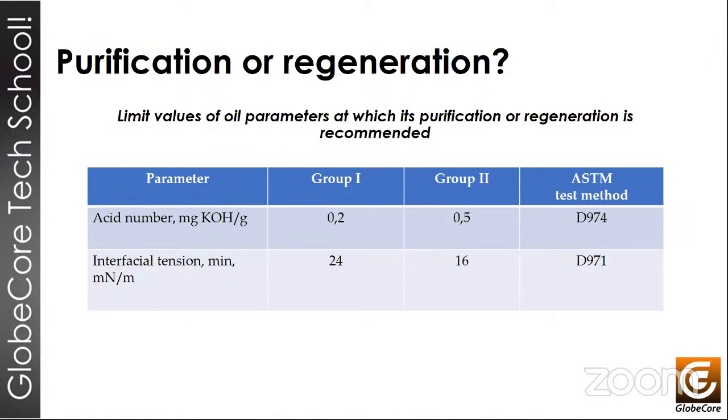When we detect some problems, we can detect them early by taking oil samples. And when we do, we can take corrective action to extend the life of our equipment and cause the least amount of damage to it. Now, understanding these changes and the reasons for the changes, and having the ability to stop the degradation process before it becomes problematic, is all important for extending the service life of the transformer, and thus for selecting predictive processes, not just corrective ones. Okay. Next slide, please.